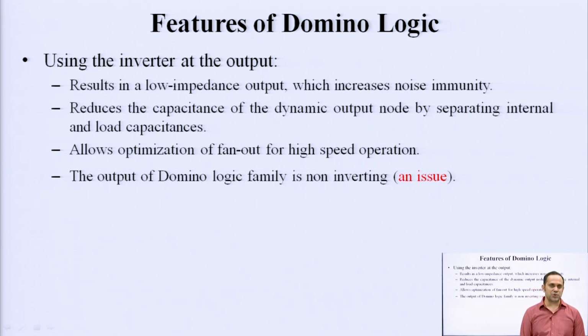This can be an issue from the scalability point of view, right, because if a setup is already ready for an inverting technology, to produce a non-inverting output and then probably at some other stage invert it again is a cost and scalability issue. Okay. So, this is one of the issues associated with domino logic, that the output is actually non-inverting when most of the CMOS logic design is an inverting design.